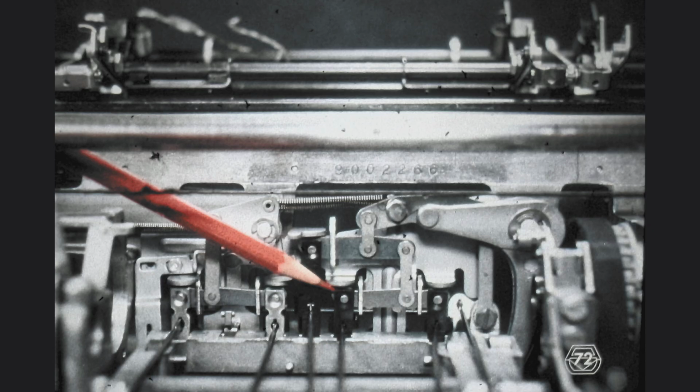Take some time to locate these latches in your machine. Pay particular attention to the location of the -5 latch. The objective of the rotate differential is to divide the motion obtained from the cam follower into 5 rotate increments in either direction. Whatever the number of increments obtained from the rotate differential, the motion is transferred through the big rotate bell crank, which you see above and to the right of the rotate differential. As seen so many times before, here again positive rotation is caused by the motor action, and negative rotation is caused by spring action.